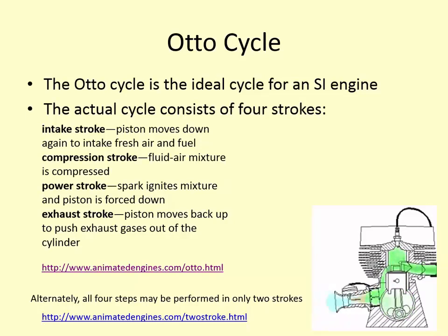Which means that the power to weight ratio of these engines is a lot higher. Their fuel economy is better because you're getting power out every other stroke, but their emissions are worse. So most vehicles cannot pass an emissions inspection if they have a two-stroke engine.